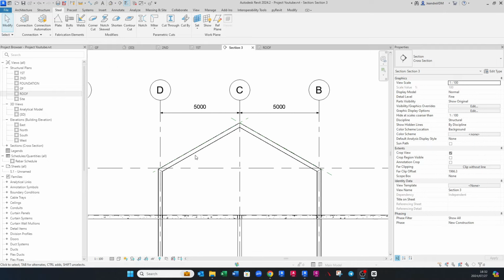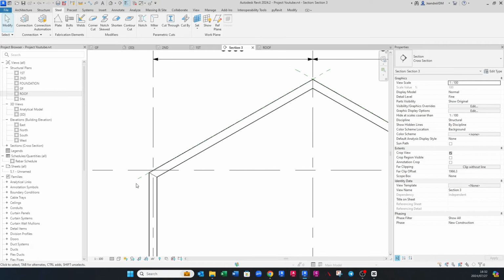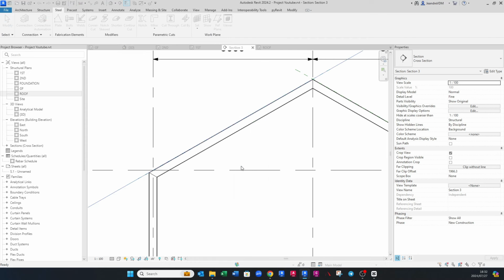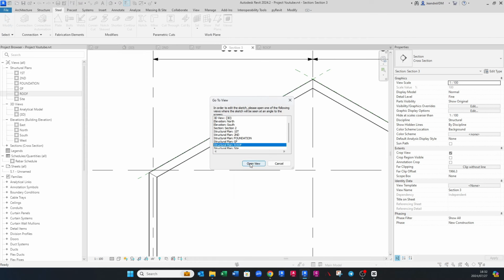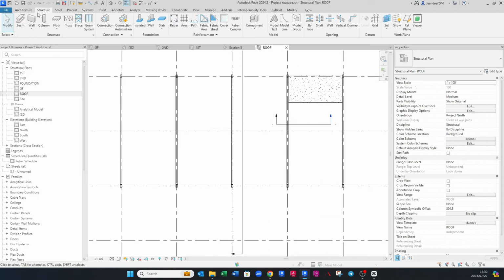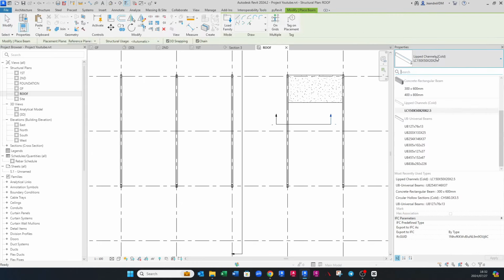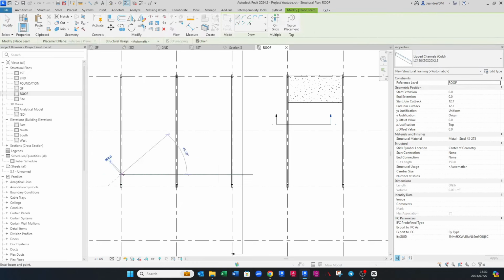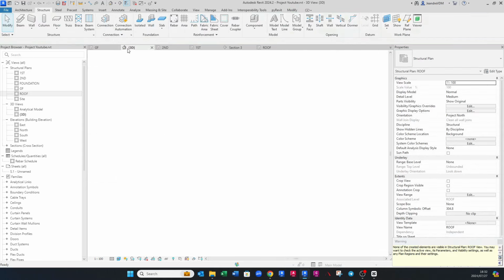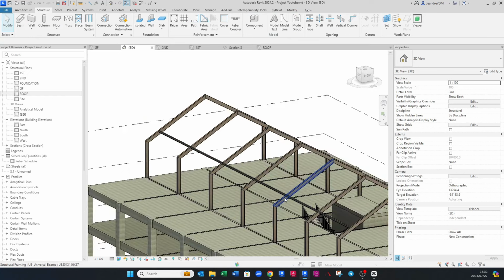Okay, now we're going to do the purlin. So we've already selected the rafter as our reference plane. Just double check it again. Set work plane. Seems like it didn't choose it. So luckily we double checked. Let's put the beam in now. There we are, selected. Run from here to there. We're not going to see it because it's at a lower level.